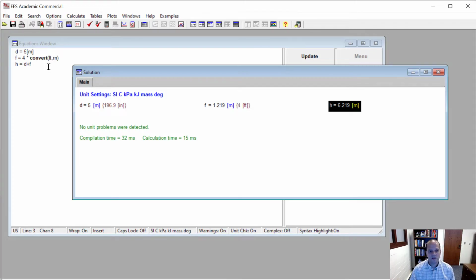We'll talk about additional functionality that you'll want to take advantage of, plotting, making use of the thermophysical properties that are built into EES. There's tables of data for water, especially. We're using a lot of those. But all the gases that you'd want to use, whether it's ideal gas properties or real gas properties, we can specify in EES, and we can look up all the thermodynamic variables that you would want to have in order to do some analysis of either a component or a loop.